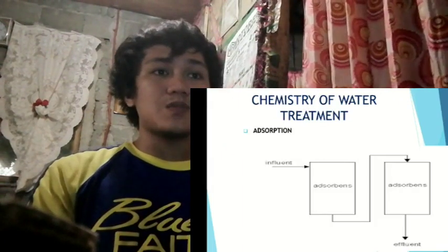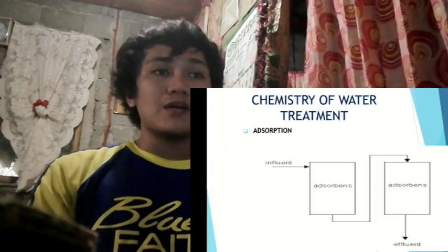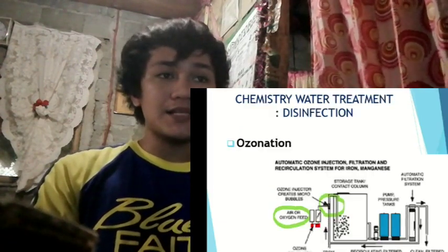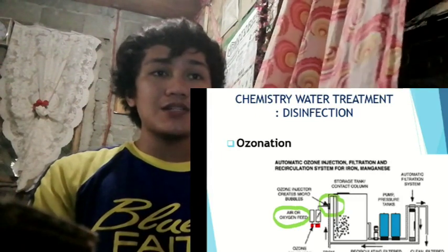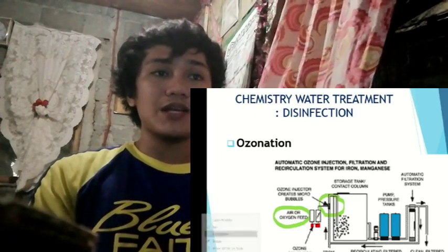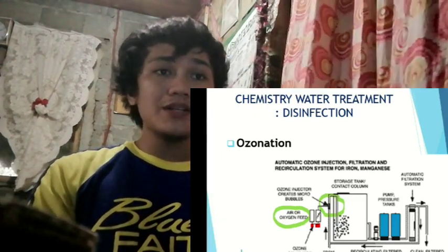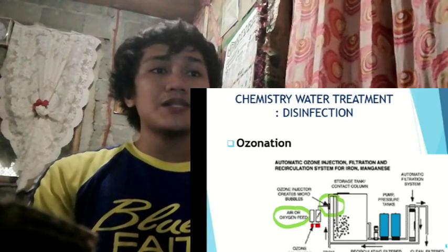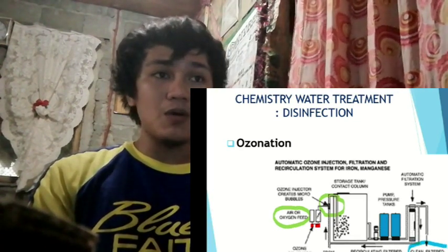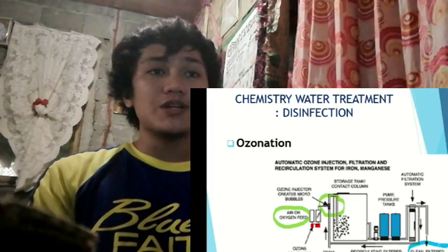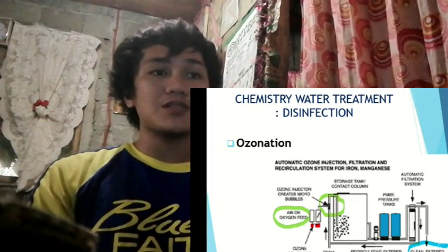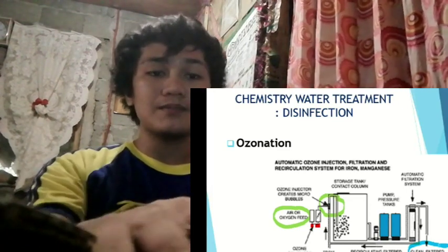Advanced oxidation processes, or AOPs, are combinations of disinfectants designed to produce hydroxyl radicals. Hydroxyl radicals are highly reactive, non-selective oxidants able to decompose many organic compounds. Most noteworthy of the AOP processes is ozone plus hydrogen peroxide.